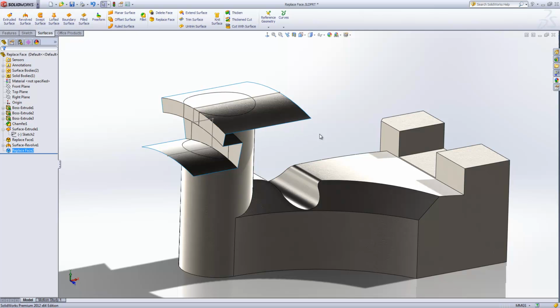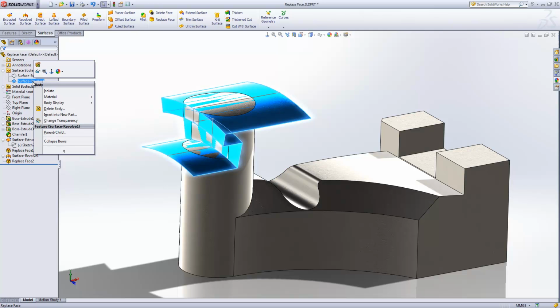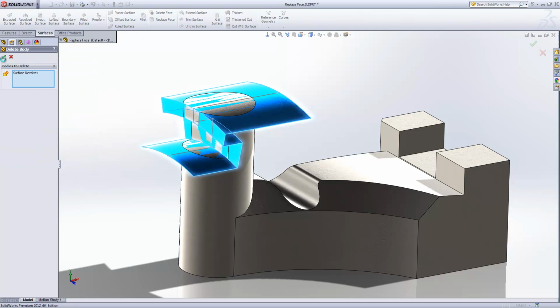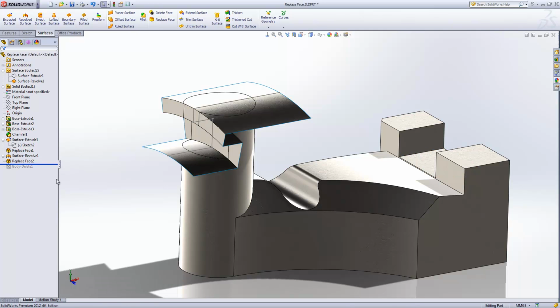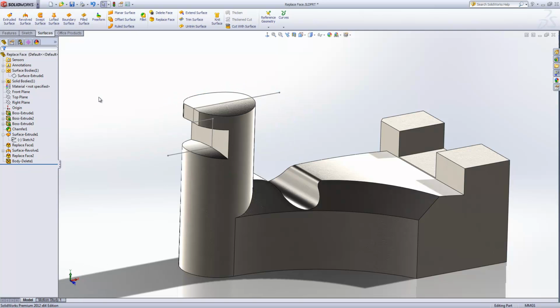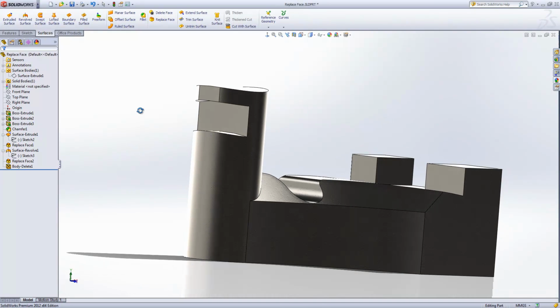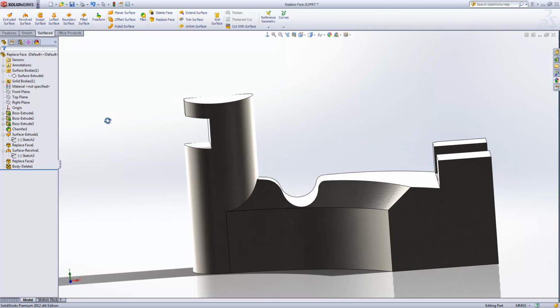again we just need to get rid of this surface. So the other way you can get rid of a surface out of a design is just to delete the body. If we go over to this left hand side, you'll see there's a surface bodies folder, and we've got that revolve surface in there. And if you're looking to keep things neat, you can right click on here to delete that body, and that becomes a feature in your tree, which obviously means if we roll back above this item, that feature will come back. Okay, so again I'll take out that sketch, and you'll see there the complexity of the result that we've got.